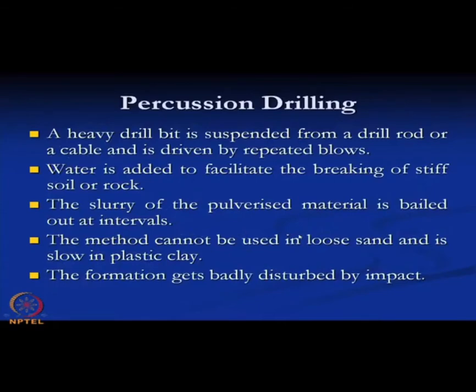So, when you are talking about this type of boring, in all the borings except the auger borings, a drill rod is there and a bit is attached in front of the drill rod, and this drill rod is pushed into the soil and driven also, and then this drill bit helps to advance the rod into the soil or borehole, and whenever a soil sample is required, this drill bit is replaced by the sampler.